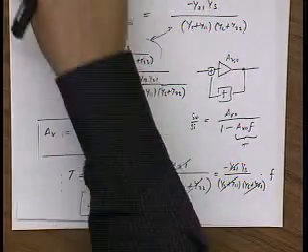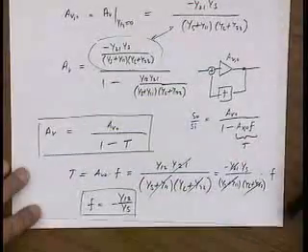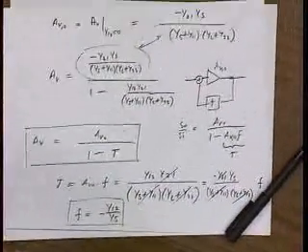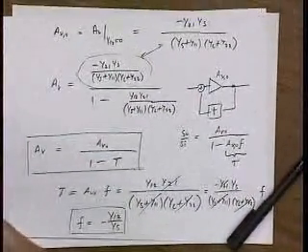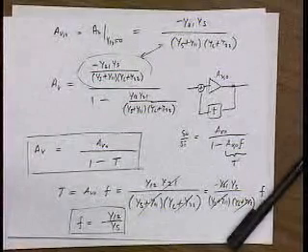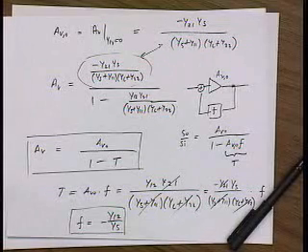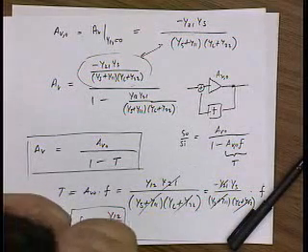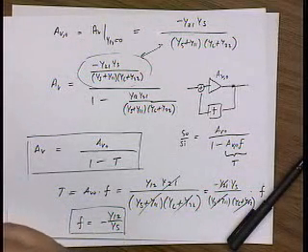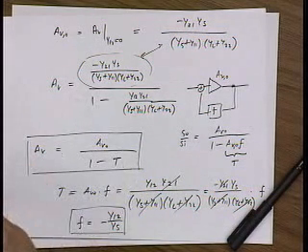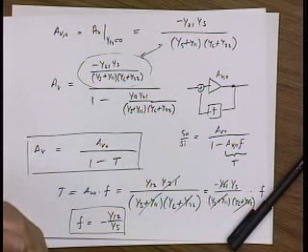Yes, Debo. As we were discussing in the last lecture, usually this is voltage driven, but because it's a shunt feedback and also the input impedance is lowered, we like to see it as a current. So if we do a Thevenin to Norton transformation, we would also end up with that current source in parallel with a series parallel resistance. So in this whole derivation, where would we fit it? Okay, I'm glad you asked that question, because what we'd like to do is design a good amplifier.